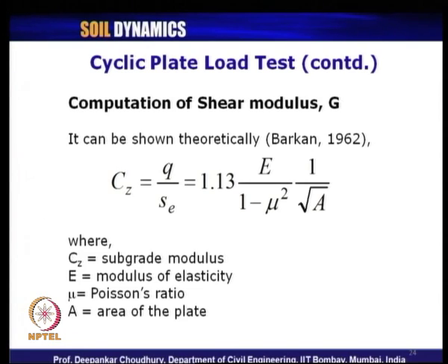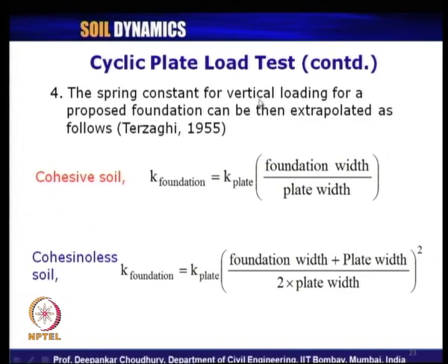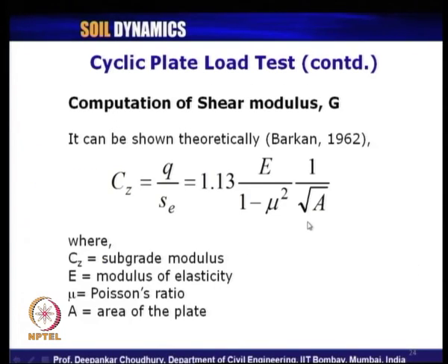For other modes of vibration, that is horizontal, rocking, pitching, etc., we will see other expressions available to correlate the dynamic shear modulus with the Young's modulus. So, this expression is, truly speaking, valid for vertical loading or vertical vibration only, as it is mentioned in the previous slide also.